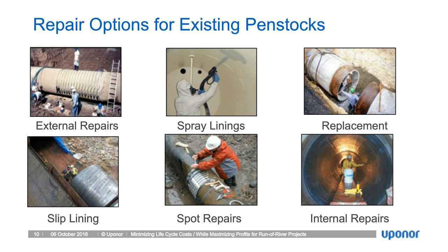Spray linings: sometimes if it's a steel pipe and you're just looking to reduce corrosion potential, or some of the linings have a better Manning's number or are slicker. Linings such as epoxy or urethane can be applied to the surface to help extend the life cycle or life expectancy of the materials, as well as increasing flow velocities because the liners typically have less resistance.